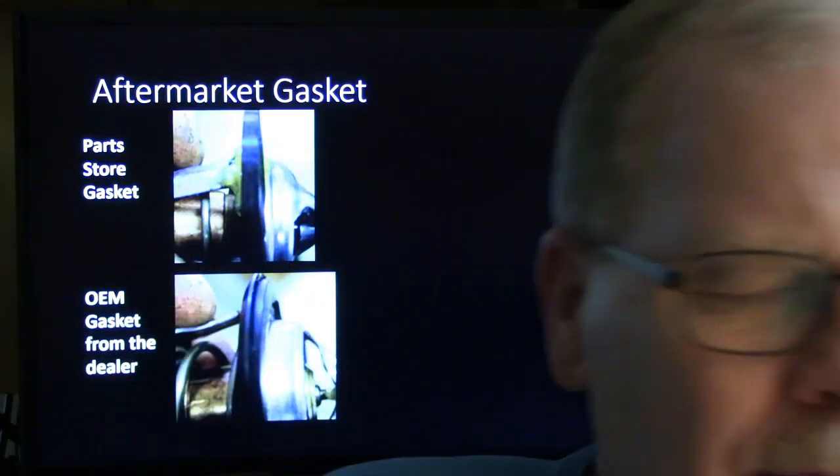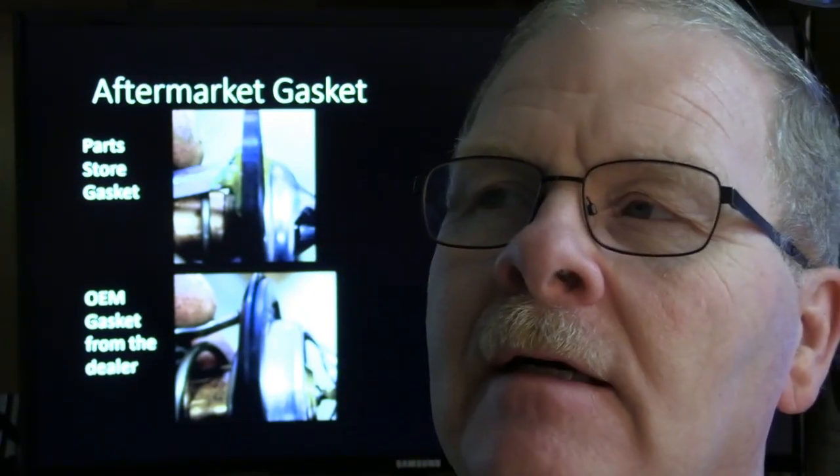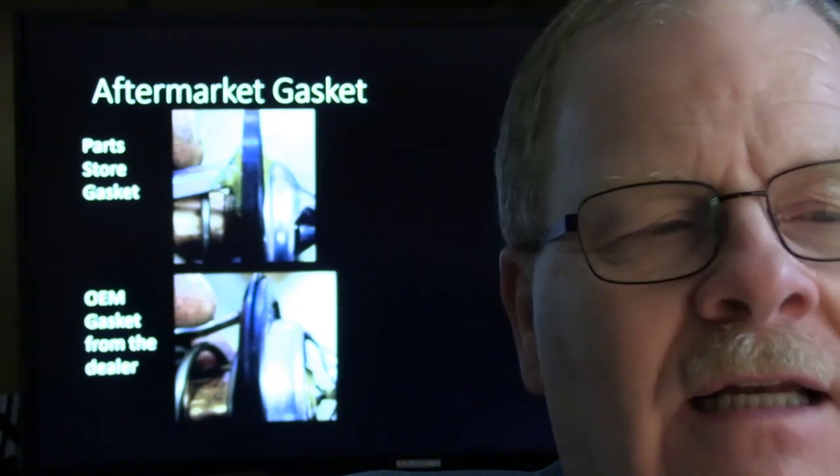But I will say that when I was fighting with a cold engine, like at the Ford place, I'd get another thermostat out of the parts room and it would still run cold, and then I'd get another thermostat and it would still run cold, and I was just like, what the heck is this? And one time I had to put 4 thermostats in before it ever started getting warm, and that was pretty disgusting.